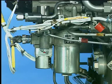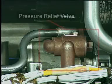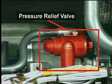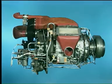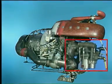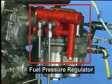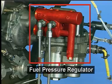The fuel flows internally through the high-pressure pump to the fuel pressure regulator and the servo valve. The pressure pump is protected by a pressure relief valve. The fuel pressure regulator supplies servo fuel to operate the inlet guide vane actuator and the bleed control valve.